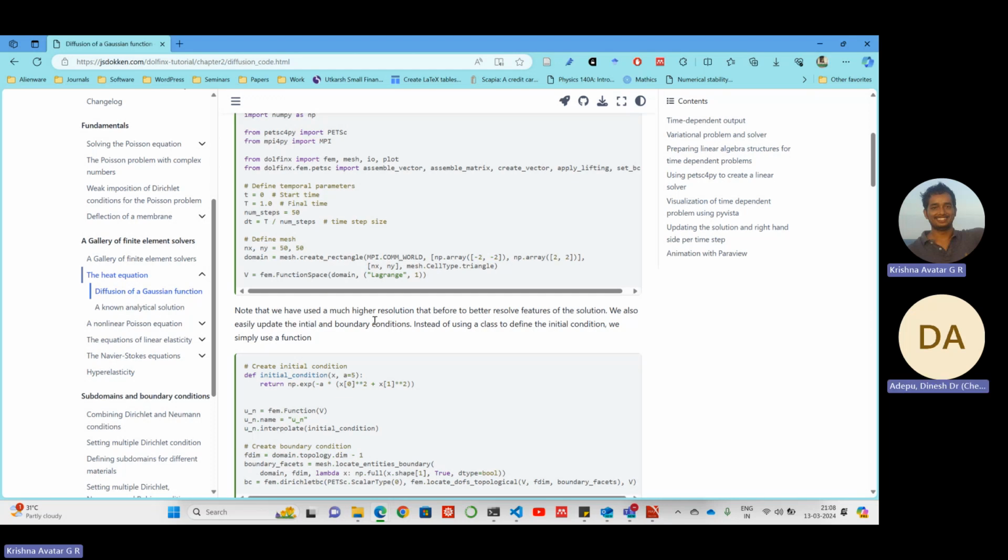However, we must mind that this bilinear form is only valid for a linear problem. For a nonlinear problem, we have to use a nonlinear solver. Provided this introduction, we can look at any FEniCS software which deals with any kind of problem, such as fluid structure interaction. Let's just see where the bilinear form is and how he's doing it, and try to understand how he's getting this bilinear form in the first place.